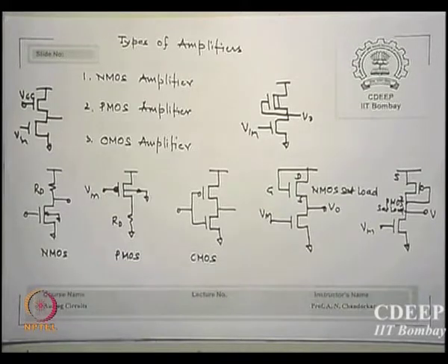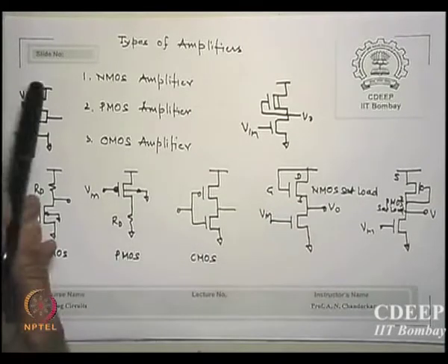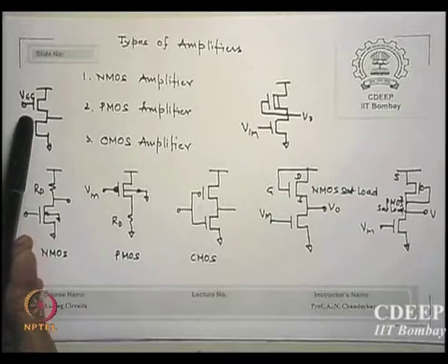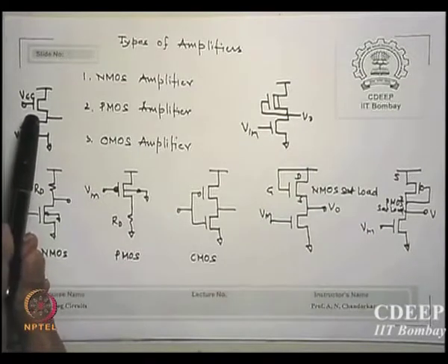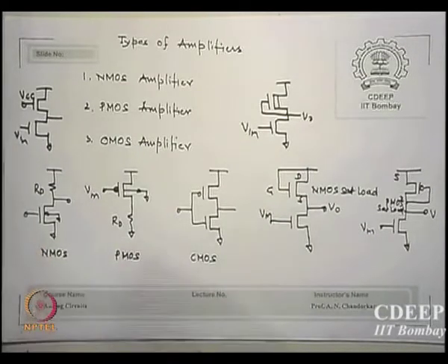So in some requirement, if you want lower resistance, what do we do? We do not connect it to VDD but to a higher voltage and actually use the linear device there. Is that correct? So that R can be further reduced. Where do you think a smaller R will be required? What does smaller R mean? Does current increase or decrease?